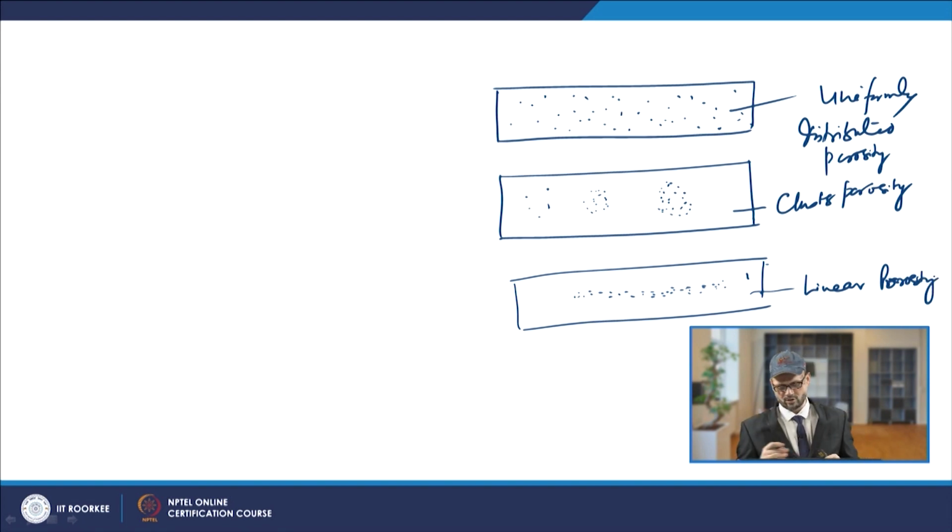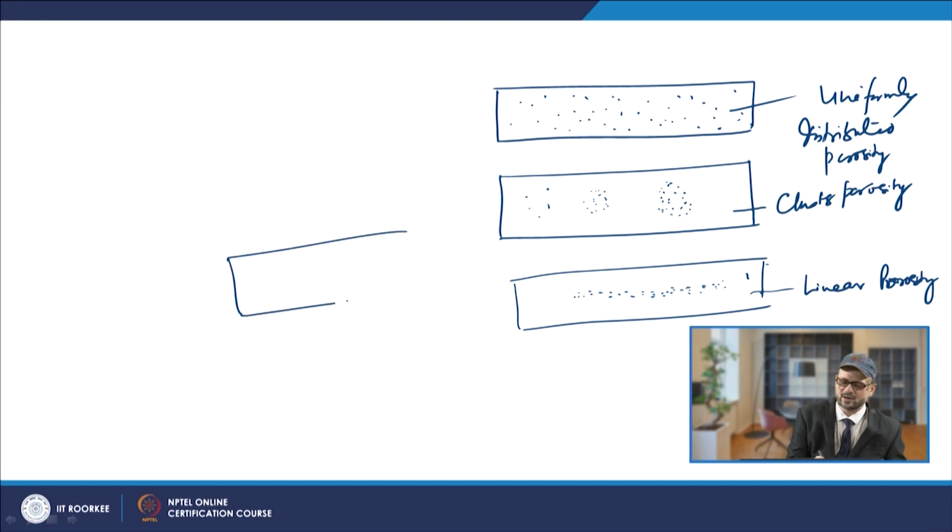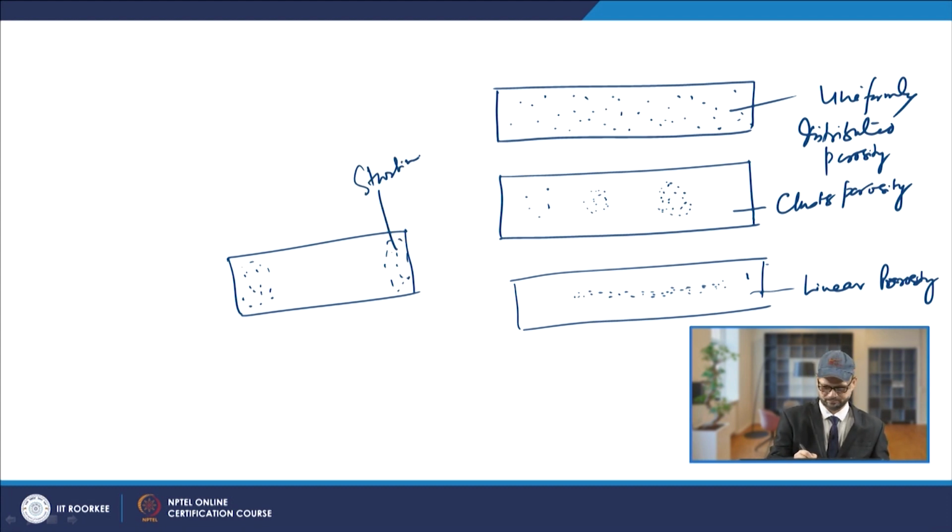It is normally in the root pass of the weld, but if you talk about the starting porosity, you will have it in the starting regions. So, this is your region. You will have these as the starting porosities. So, you have different types of porosities which are normally come across in the case of the subsurface defects.